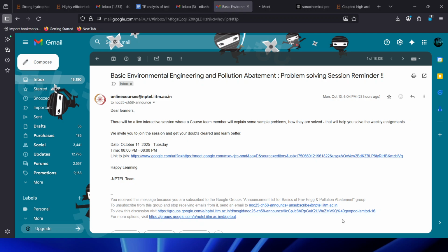I mean, water is sprayed as very fine droplets. When we have such small droplets, they can easily interact with the dust particles or particulate matter. If you have a very high stream or a jet, then the particles will not come in contact with water properly. It will repel them. I mean, not repel, but it will prevent their mixing. So that is why we use very fine droplets in wet scrubbers.